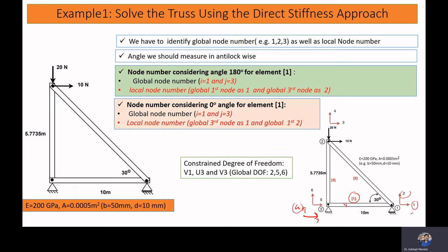Once you obtain the stiffness matrix in the global coordinate, you have to assign the global degrees of freedom. If you obtain a 4 by 4 matrix, 1, 2, 3, 4 is for the local coordinate system. Again you have to assign global degrees of freedom so that you can assemble it easily. The trick is that you can assume any node numbering, provided you stick with it.